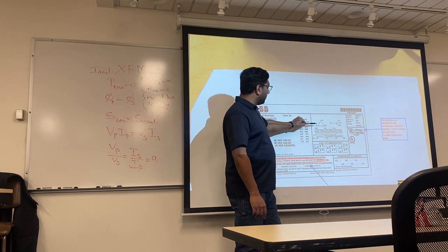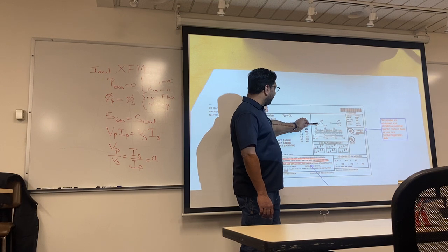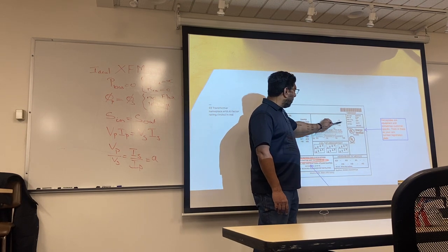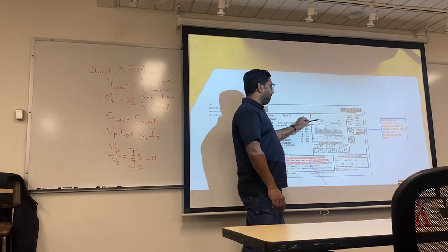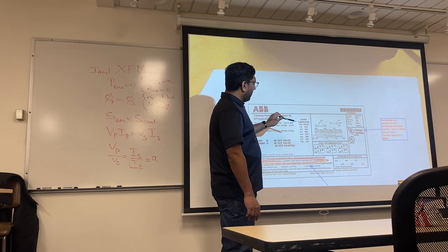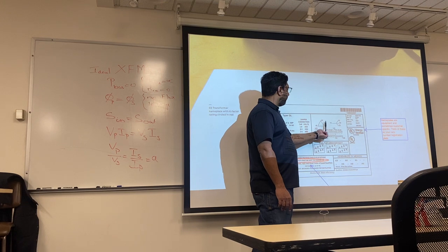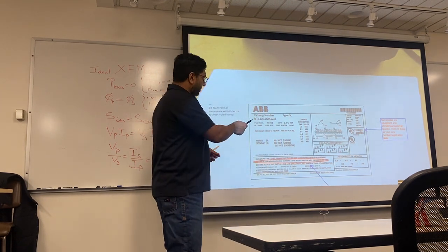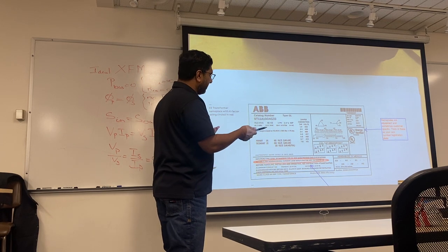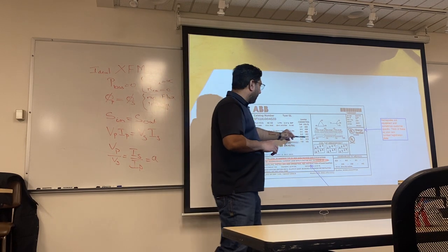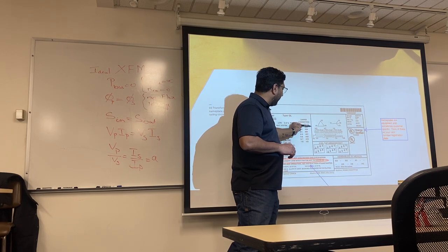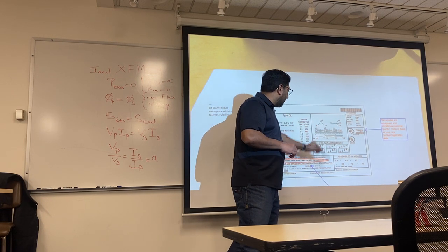In other words, this solves a lot of issues for me. You have a delta on the high side and a Y on the secondary, and that's how you get rid of harmonics in one way. It introduces other issues, like there's going to be a phase shift, but there is no chance of the harmonics that happened in the delta jumping onto a Y system.